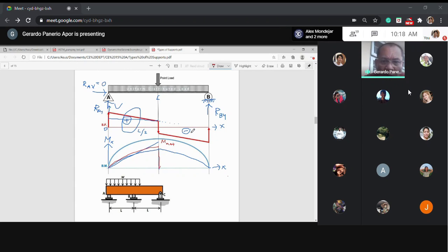It is minus. Why minus? Because it is a negative area. So instead of adding, it subtracts. So as you go from midspan to the other end, it is always minus. The minus keeps increasing, the bigger the minus gets. Like that. Now, it goes back to 0. Why? The positive area and the negative area are the same. So, surely it goes back to 0.